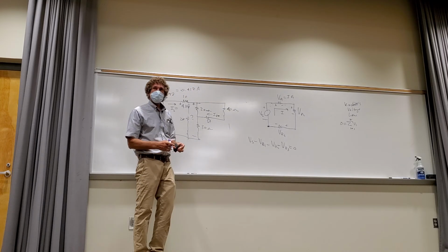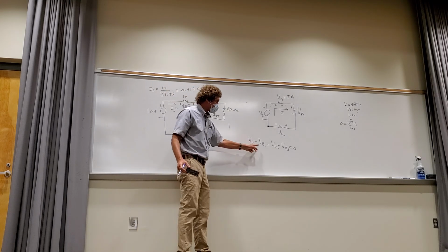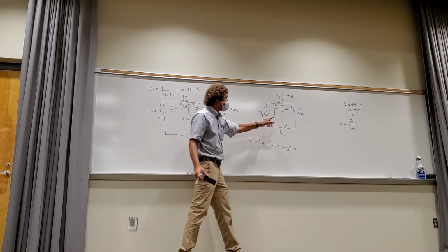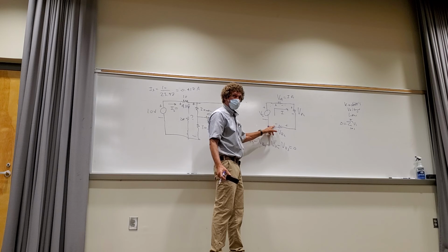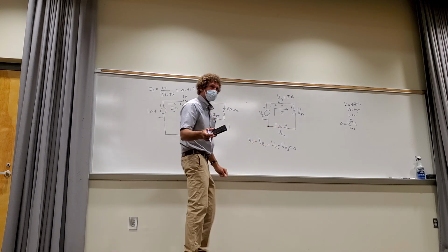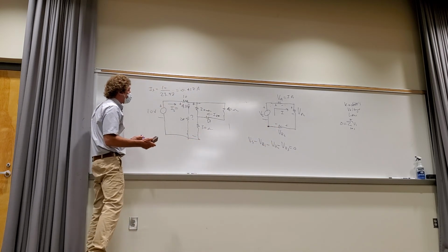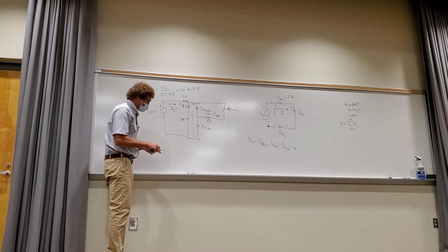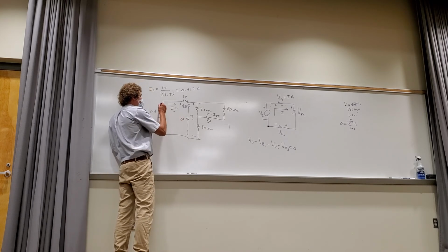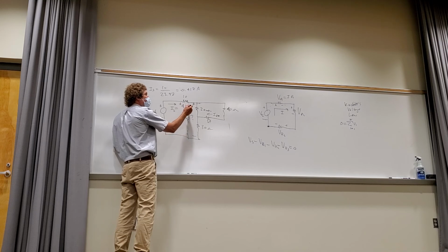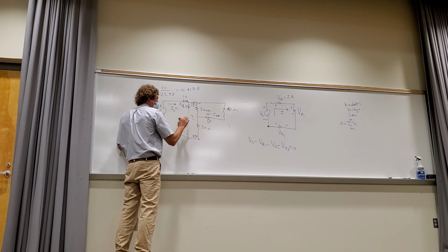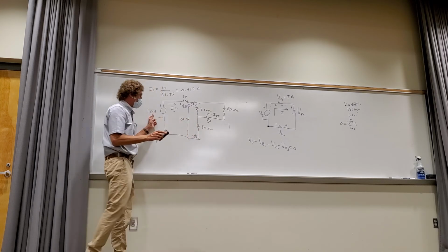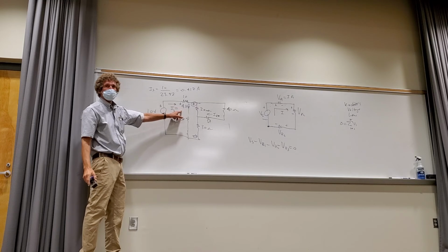But my point is this. I took the source voltage and I'd subtract VR1 if I wanted the voltage between here and here. Are you with me? I'm moving a little faster because I got 5 minutes. So now what I can say is this. Please watch this. I know I've got 10 volts here and I've got 4.17 volts here. So the actual voltage remaining between here and here will be equal to 10 minus that value. How many see that?